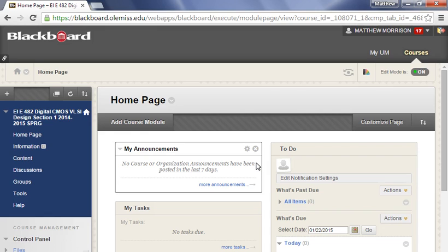In this course, we're going to start at the transistor level and build up. In the first few lectures, we're going to learn how a transistor works, a MOSFET, which stands for metal oxide semiconductor field effect transistor. CMOS, the general idea is that you have to work them in complement. You have a pull-up network with positive metal oxide semiconductors, and you have negative metal oxide semiconductors, and they work in complement, CMOS, complementary metal oxide semiconductor. So you can work these pull-up and pull-down networks, and we're going to be building these up.